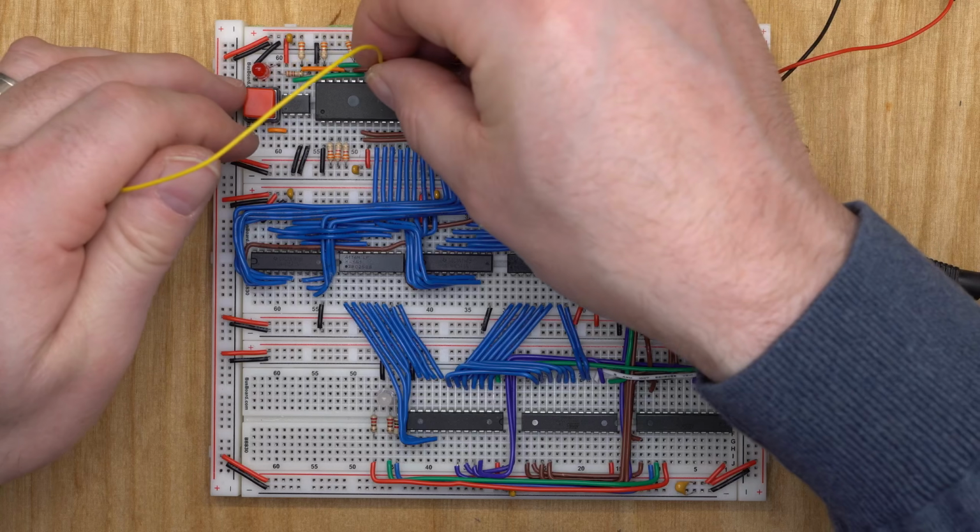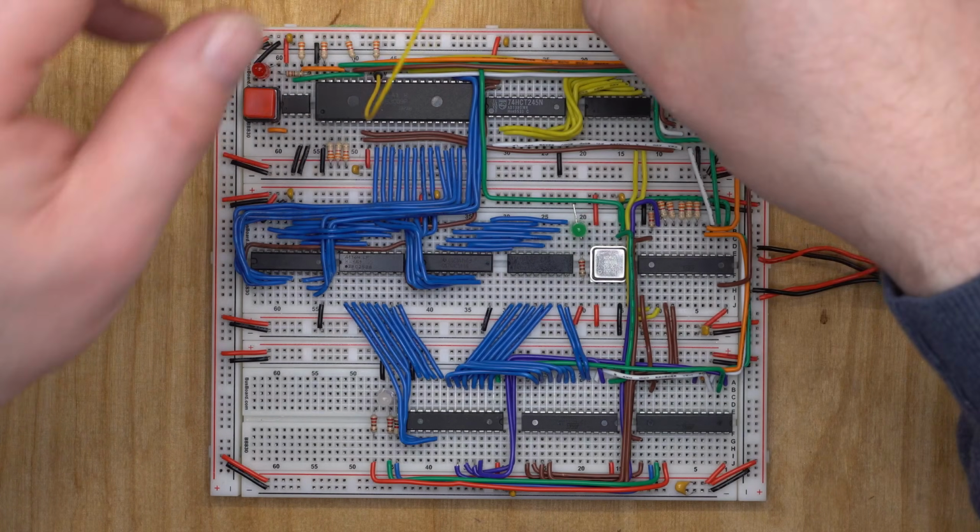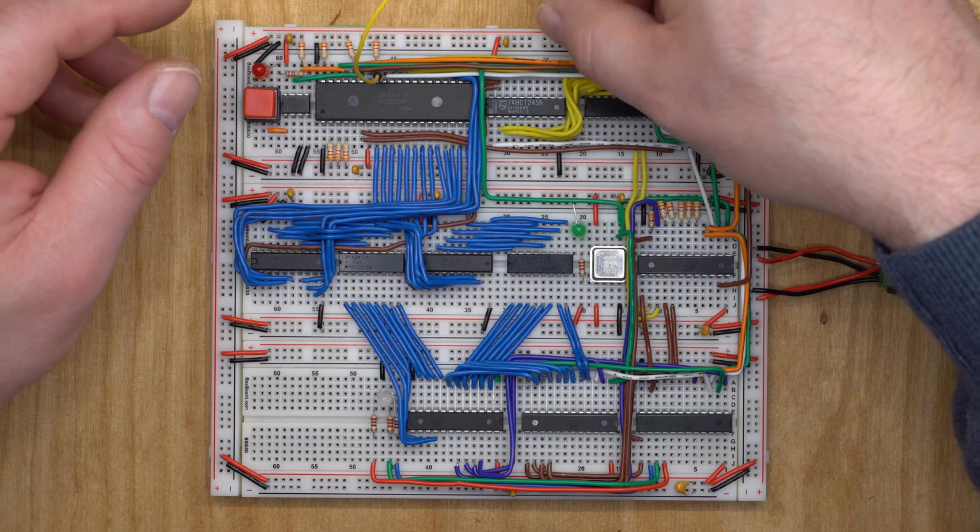To do that safely, the bus request line is held low so we can simulate proper bus conditions without the CPU going rogue. I wanted to use the Arduino Mega to simulate all the conditions, but this episode is getting long as it is, so I'll do a quick manual montage of the testing process.